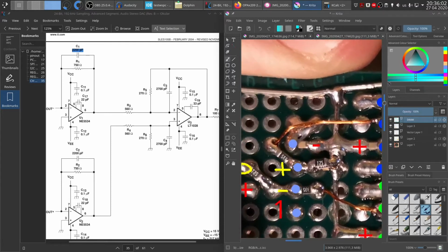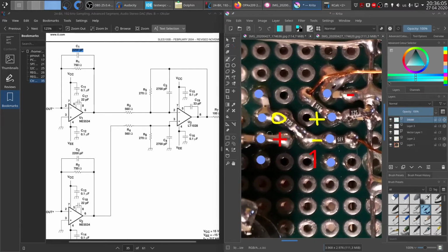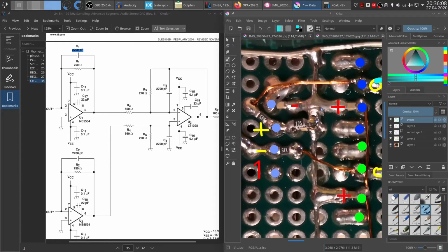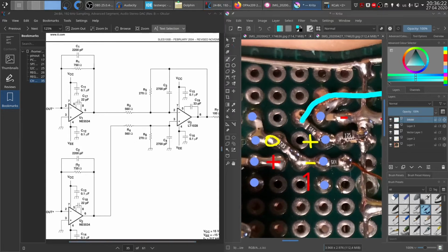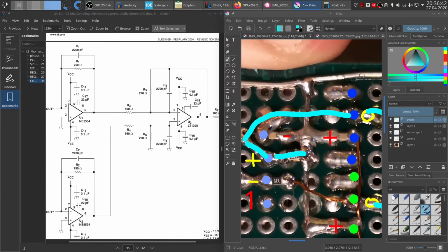In this purplish dots, this is this amplifier. So we can see that the output over here goes over this jumper wire to this pin over here, which is not connected to the amplifier directly, because it firstly has to go through this resistor before going to one of its pins. It goes firstly over this 560 ohms resistor before connecting to the plus terminal, and then it's another 270 ohms resistor to ground. So this long lead is in this case ground because it goes everywhere.